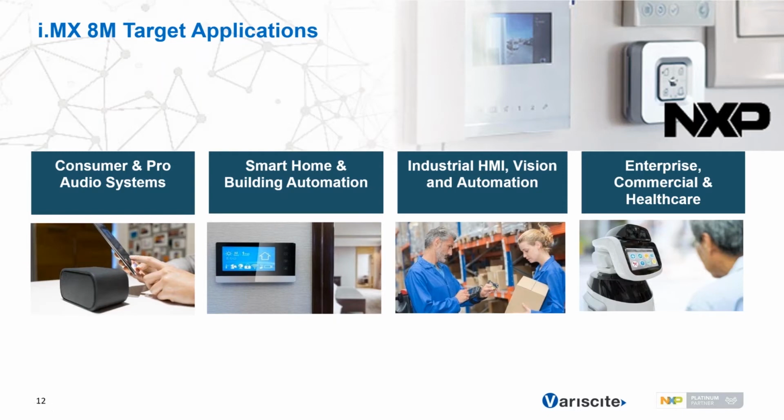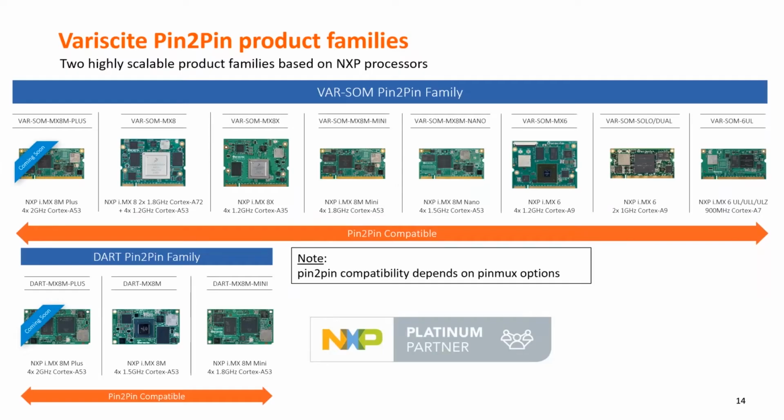Thank you, Ofer. Yeah, thank you, Robert. As I mentioned before, on top of the fact that there is scalability within the i.MX 8 processors themselves, like in between the Nano and the Mini, or the different flavors of the Mini that can be single, dual, or quad-core, Variscite practically designed two families that are pin-to-pin to each other. The Varsome, as we call it, which is an edge connector of 200 pins, and below that, the Dart pin-to-pin family that is based on 3 board-to-board connectors that are sitting at the back.